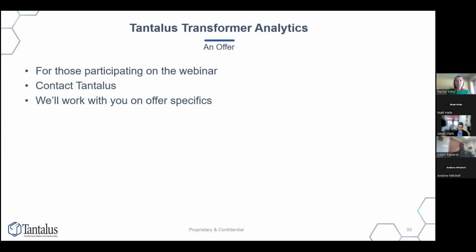Yeah, we found some of that, where they were labeled, mostly with different voltages that didn't make sense. It presented weird when we looked at the transformer loading, because we had some that were 120 volts, and you're like, well, it can't be off this transformer. So looking at that, there were some ways to do it. We were able to go out, look at that actual meter, confirm it's definitely not connected to this one, and then get into our mapping and update it. Once we had that updated mapping, it was easy to pull a new file into the Transformer Analytics, and that resolved the issue. And there are other ones.